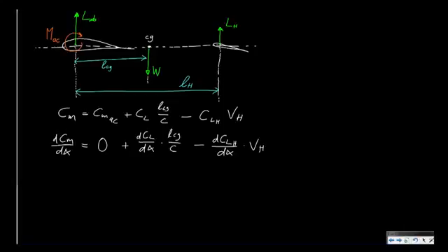So we are nearly there. These coefficients are easily obtained. The dCL/dα: you will just go to your aerodynamics guy and he will give you the lift curve, and he will say, okay, normally you're flying in this region where CL changes in a linear fashion due to alpha, and you will just have to use the steepness, which we often call A. A is simply the dCL/dα, the constant part. He will give you this number for the airfoil and you can just use it.